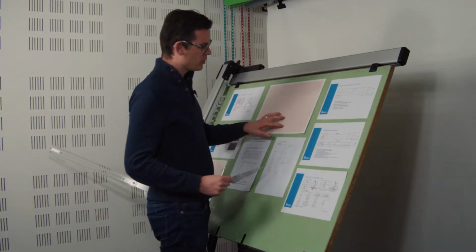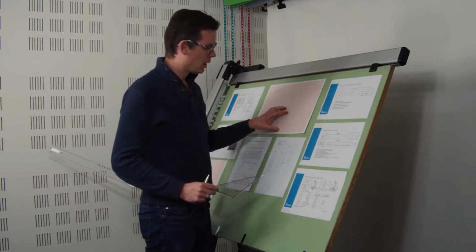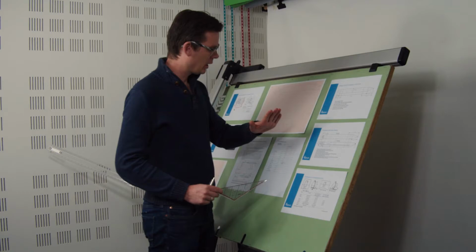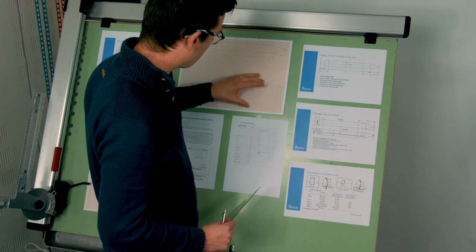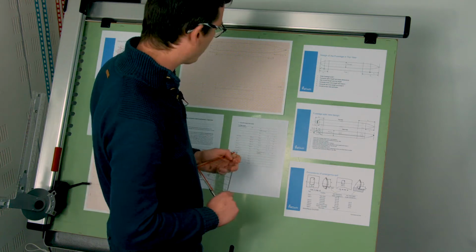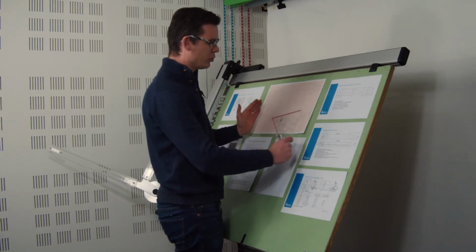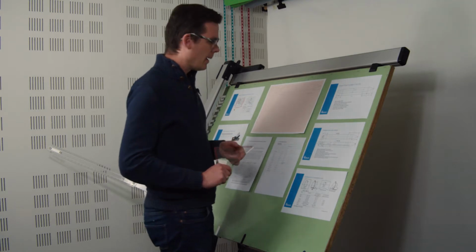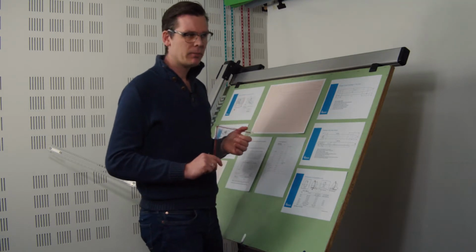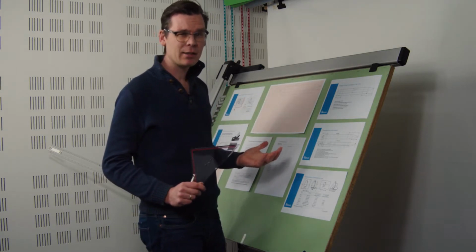Now, let's first focus on that tail cone, because that tail cone in the side view is not going to be symmetric, because the airplane needs to be able to rotate, and if we were to make it symmetric, the lower part of that fuselage would easily touch the runway, meaning that the airplane cannot rotate so much. Or if you ever want to make a stretched version of this airplane, the stretched version would have a harder time rotating. So I'm keeping that already in mind. Of course, you can rotate also a symmetric fuselage, but you would just need a longer landing gear.